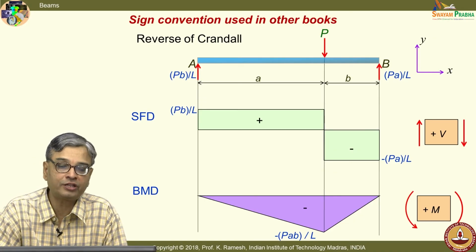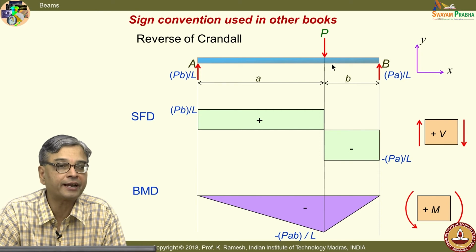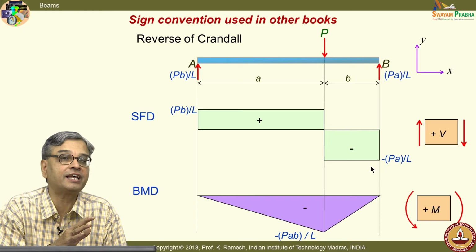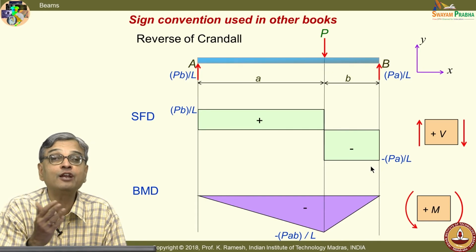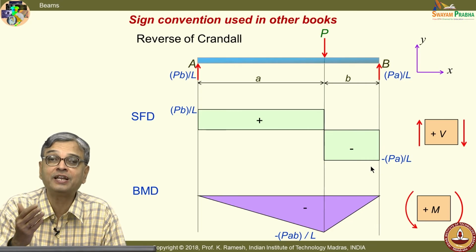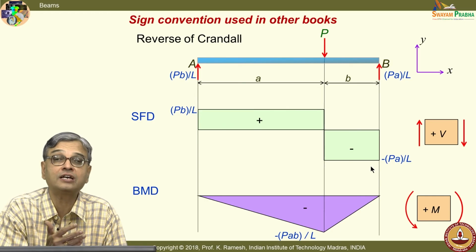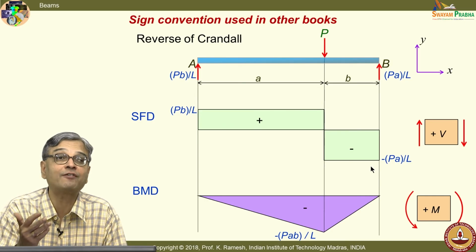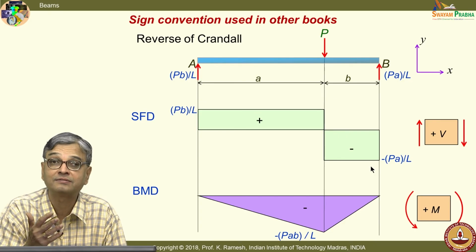And always put the bending moment and shear force diagram below the loading diagram, so that if you have made any mistake, there is a chance for you to reflect and go back and redo the calculation, or at least mention something has gone wrong somewhere. You should be alert. Both doctors and engineers have to be definite in their answers. They should not be ambiguous.